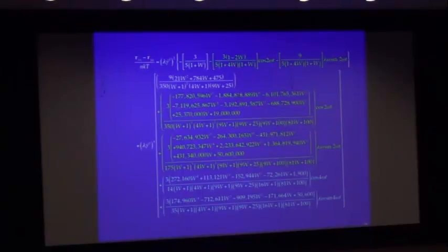We talked about viscous dampers before, but our collaborations with companies that use and design the fluids for viscous dampers, companies that make farm machinery, for instance, can now answer questions like, what will happen if I double the molecular weight? Remember the molecular weight, this quantity lambda goes with L squared, so if I double the molecular weight, lambda will increase by a power to the fourth, and then these are forces they'd rather not have, right?